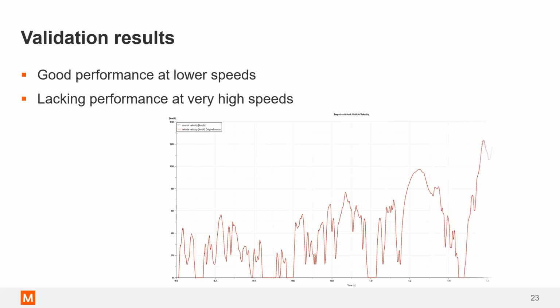The problem was when we got to the very high speeds. And you can see just as we got up to our highest speeds, where we might have on paper met the requirements for power at the certain speed, the motor couldn't quite deliver enough for that last little bit of acceleration at the high speeds, and it was just tapping out.